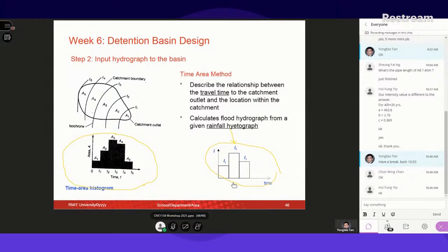So the hyetograph can be developed based on synthetic rainstorm profiles. Remember there was one question from the students about whether the maximum is at time 0. Actually, it's not time 0, because it's symmetrical. Normally the maximum is at the mid of the time period. Because it is symmetrical, we need to consider both sides if we take the profile.